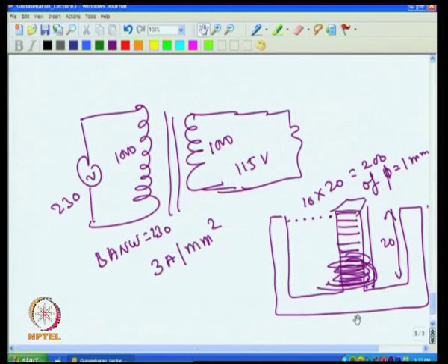This is how the transformer is to be designed, and I explained this transformer design at this point of time because we will be using this at very many places in the analog course. For example, we will be using LVDT, where we have to wind the coil. We will be using a current transformer to sense the current, where we have to wind a coil, and we will be using filters, where we need an inductor, which we will be designing.